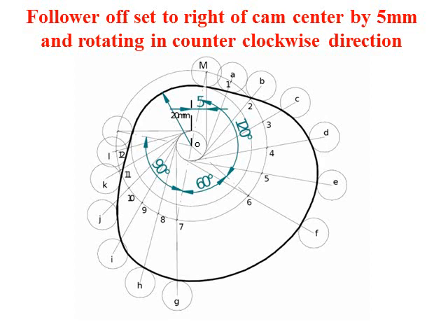Measure it by using a compass and come back to the CAM profile. Here again take 1 as the center and transfer the distance, that is mark 1a. Same way do it for 2a, and with 2 as the center, cut an arc and mark it as b. Same way we have to mark the remaining values, that is c, d, e, f, and up to k, l. Next, although it is not shown in the sketch, we need to join all the points, that is a, b, c, d up to l, and continue and join it to m. So that becomes the pitch curve.